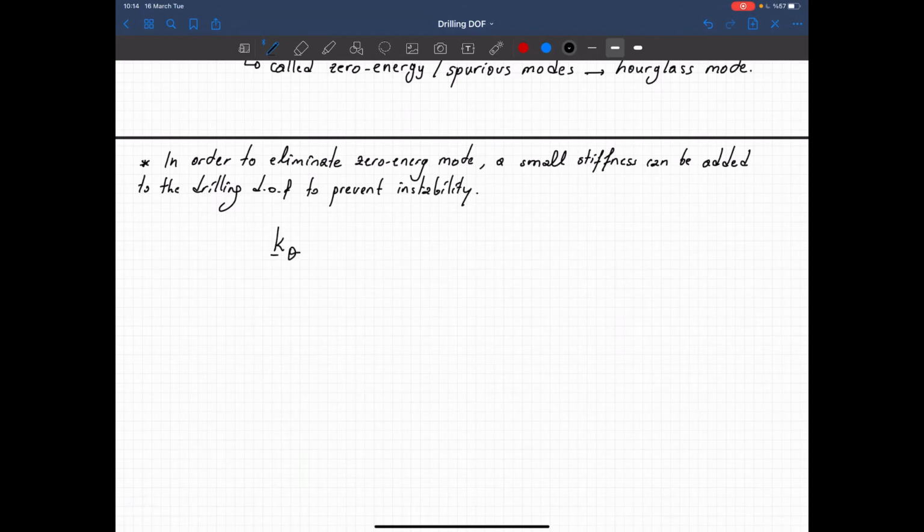So I'll just call it K theta is equal to 1/36, a coefficient alpha, elastic modulus times t to the power n, multiplied by the area of the element, and the matrix will have the following form: 1.75, minus 0.75, minus 0.25.